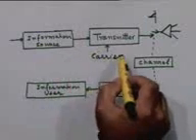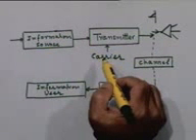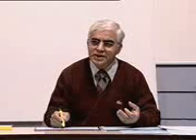That brings us to what the transmitter has to do. The transmitter has to embed this information appropriately into this carrier. And typically this is done through a process called modulation. You modulate a specific parameter of the carrier along with the signal. For example, the signal might modulate the amplitude of the carrier. Depending on the amplitude of this analog signal here, you modify the amplitude of this carrier.